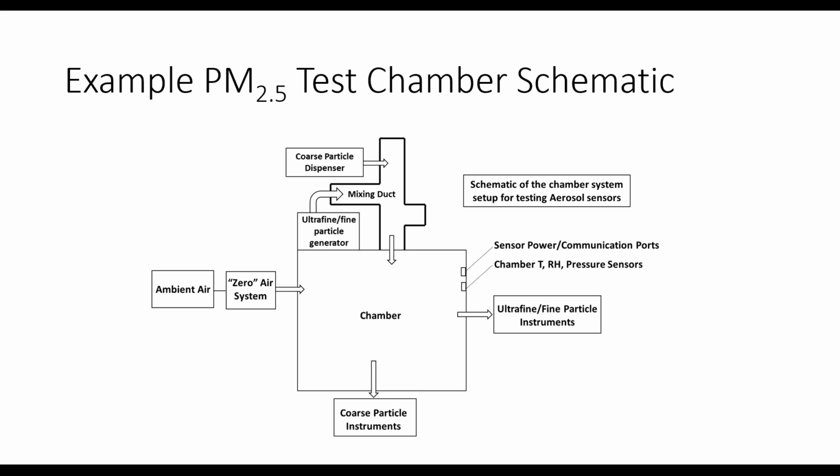And then we introduce PM2.5 into the chamber in a controlled way. And in this test method, you would need some sort of fan to move the pollutant around in the chamber. We don't specify CFM or anything like that because that's going to depend on your chamber volume. But they essentially have to be able to mimic the test conditions as written in the test method, which establishes a steady state metric for that chamber.